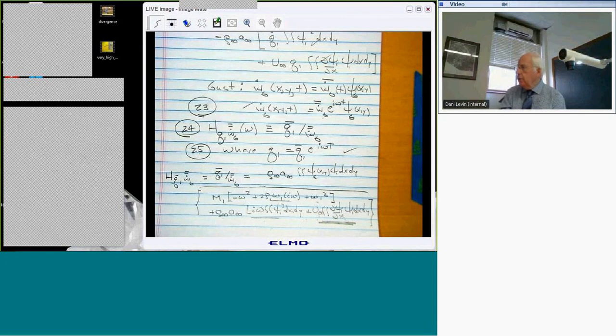Theoretically, and even during the design phase, there's another kind of flutter that can occur, which we will talk about. But if it's a competent group of aeroelasticians, hardly ever does that kind of flutter occur in practice, because the people are so good and the theory is good enough that they make sure that doesn't happen. So often when you have flutter in practice, you tell me this, right? With an airplane, it's usually on the tail horizontal control surface, possibly the vertical surface, and it's often due to negative aerodynamic damping. Why? Because the theory isn't as good in predicting.